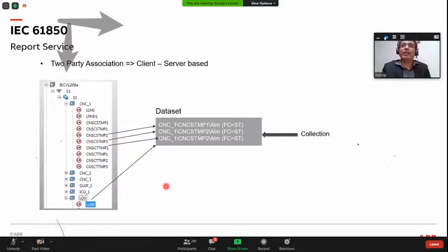There are some terms which are used specifically in 61850 language. You might have seen this diagram, you have many logical devices, the collection of logical nodes, and as a substation automation engineer I'm interested in sending only this conductor temperature, which we have designed before, and the alarm status to the SCADA. So what is the first thing I will do? I will collect the data from here. There's an engineering procedure, so I collect the data through engineering.